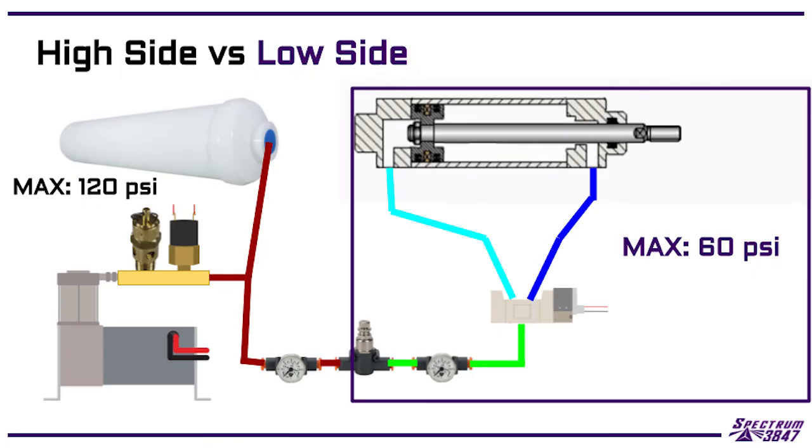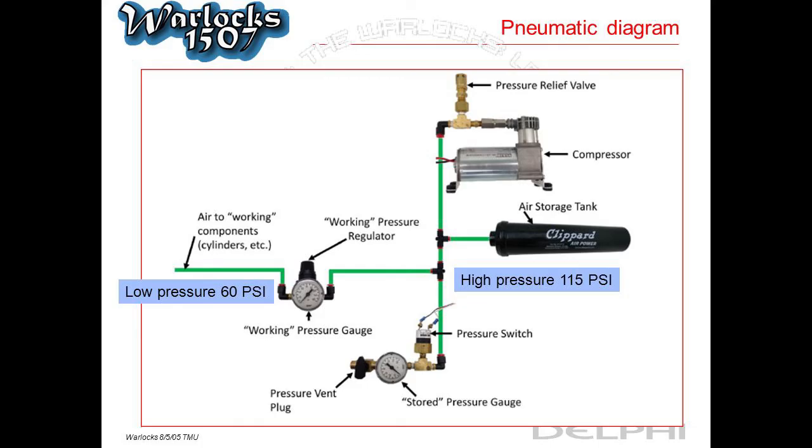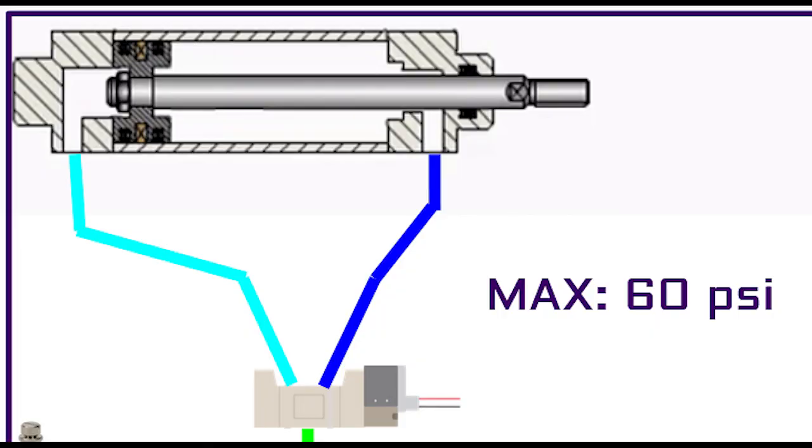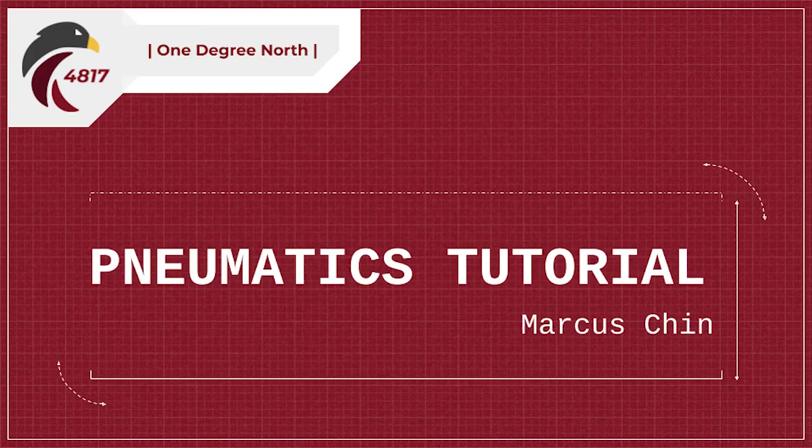As long as we separate our pneumatic system like this, the configuration doesn't really matter. And although there are some specific places where order does matter, these usually make sense. For example, we always put the piston after the solenoid because the solenoid controls the air that goes into the piston. That's pretty much all of how to create an FRC pneumatic system. We created one in the lab the other day, so here's a video of it working.